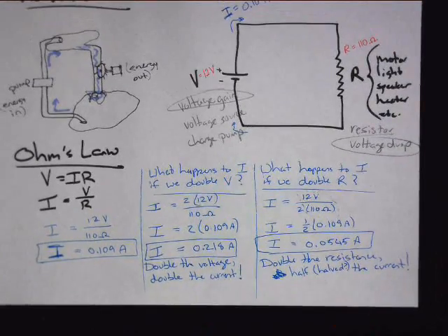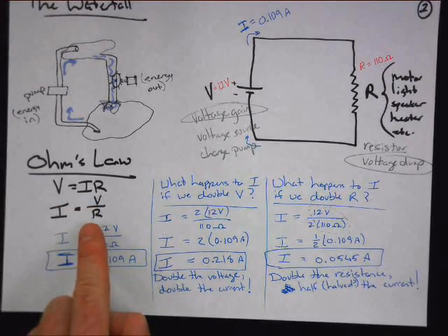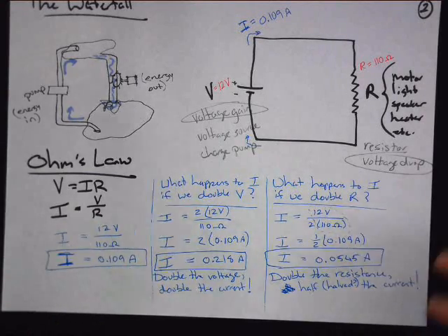That's also important to realize. Double the resistance, current is cut in half. Double the voltage, current is doubled. And that all comes from Ohm's law right here. Awesome. Some interesting questions coming next, however. And so we have to address this.